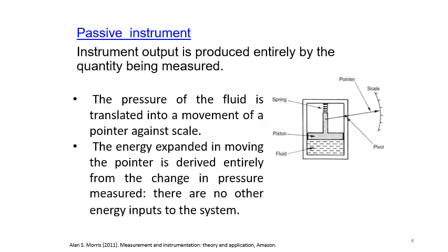How about passive instruments? In a passive instrument, the quantity is directly measured without converting it to electrical. If you look here, the pressure of the fluid is measured by the change of the piston position, and this piston is connected to this pointer. As the piston goes up or down, the pointer changes its position.